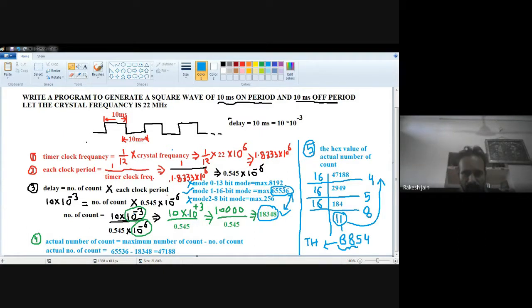If we choose timer 0, then the upper timer register is TH0 and the lower register is TL0. TH0 and TL0 are both 8 bit. If we choose timer 1 for our programming, then the upper register is known as TH1. H is for higher bits, T for timer, and 1 or 0 is related to which timer you use.